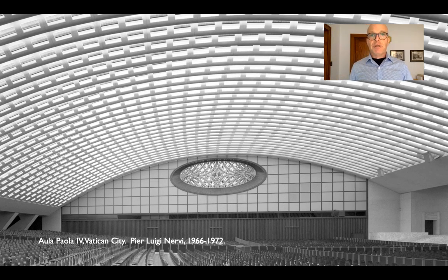So for example, Pierluigi Nervi's work, great Italian engineer and builder, we can look at it sort of squinting and say, oh, here's a funicular shape, it's an arch, it's roughly a catenary arch. In other words, if you take Saarinen's airport, flip it upside down, you get Nervi's Alla Paolo. However, if you look closely, you can see that this funicular arch is made up of hundreds of little components, all of which are hand fabricated, have to be brought to the site, have to be lifted into place.